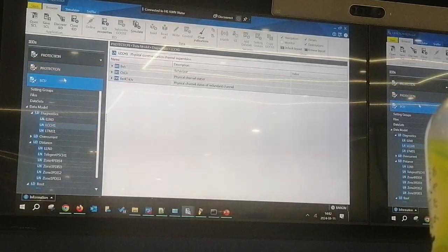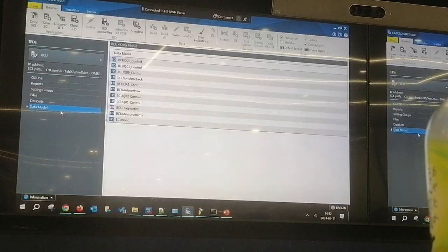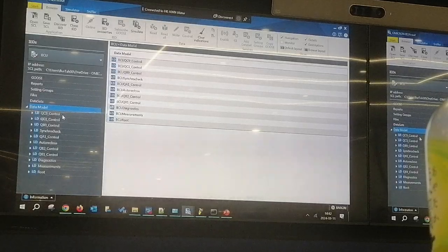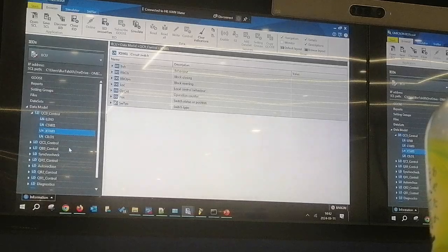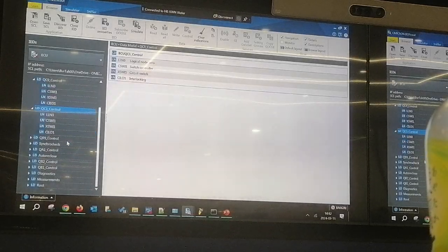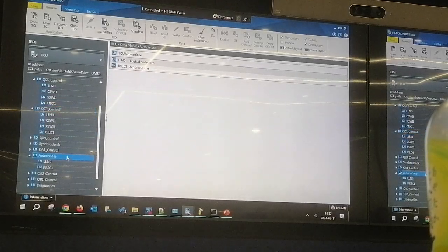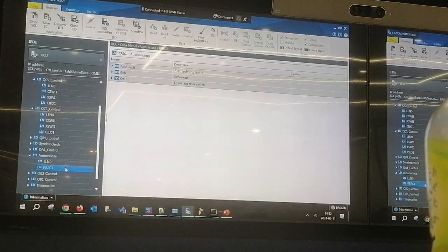Okay, let's look at the Bay controller. And even there's no IP address, you see. Nothing defined on the data model. It's more the control functions: CSWI, XSWI, cycle1, auto reclose. I don't know why I put recloser in here. Maybe recloser for me, because there are different flavors, right? You think that it's a design issue at the end.